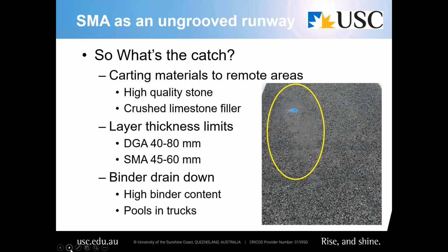The only other catch is this binder drain down. I mentioned to you about the fibers to try and stop this from happening, but even with the fibers, if you fill up a whole bunch of trucks at the start of the night before you start resurfacing or paving the asphalt, then the first truck is at risk of some of this binder pooling in the bottom of the truck because it's going to be standing around for probably a couple of hours until it actually gets used. The photo on the right shows an example from Emerald Airport. There were 3 of those, I think, from memory. They were all the first truck of the night.